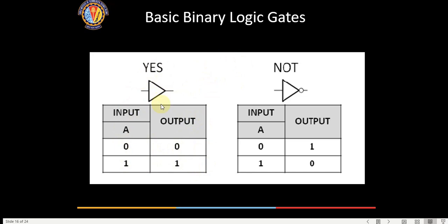Whenever you have a processor which is doing some computation, and it is giving an output, that output you might have to transmit to a different IC, to a different PC. So you can use a buffer which will isolate the input and output. It will not amplify. It will ensure that the output currents are provided from the power supply through the buffer, and the computational device is not getting loaded. So it isolates output and input. This is also an important gate which we generally use as a buffer.